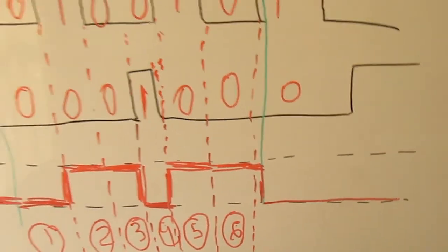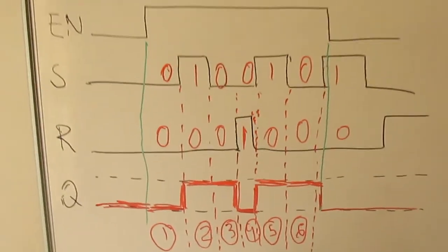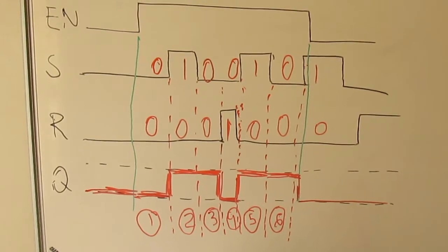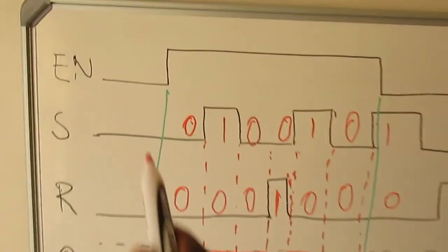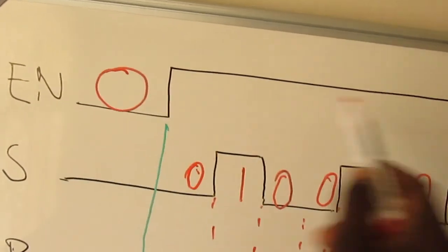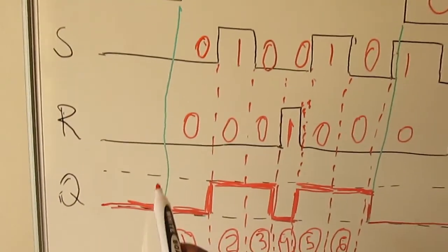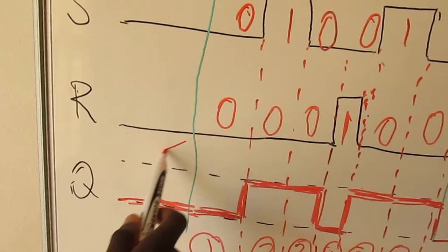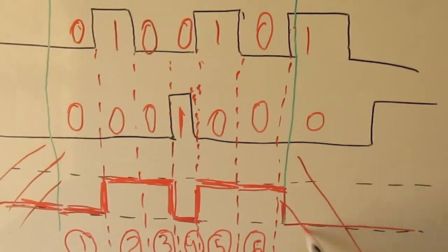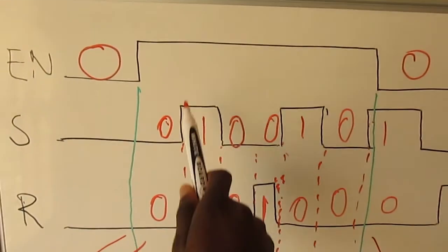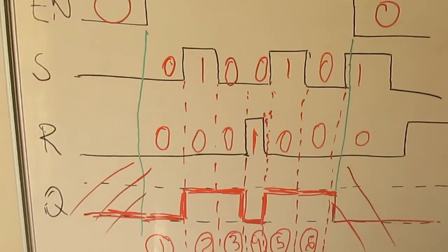Can you see? So the enable gate is like a gate which allows us to follow the data. Everywhere where our enable is 0, like this part, you have a 0 there, a 0 this side, which means already on the input, you're going to have a 0 output there and a 0 output there. We follow the data only where our enable is 1.